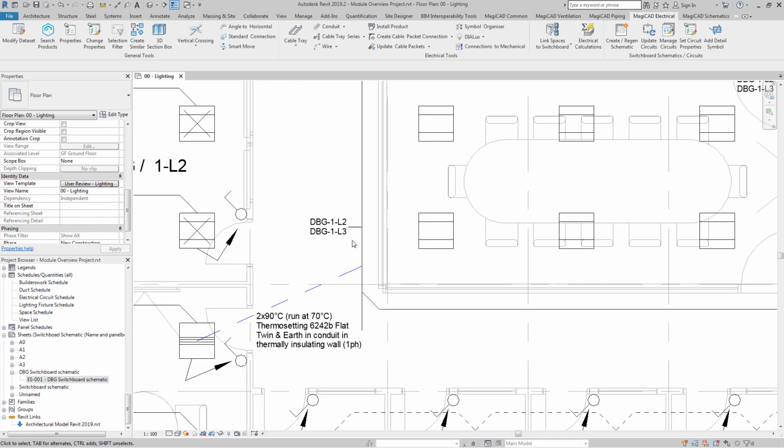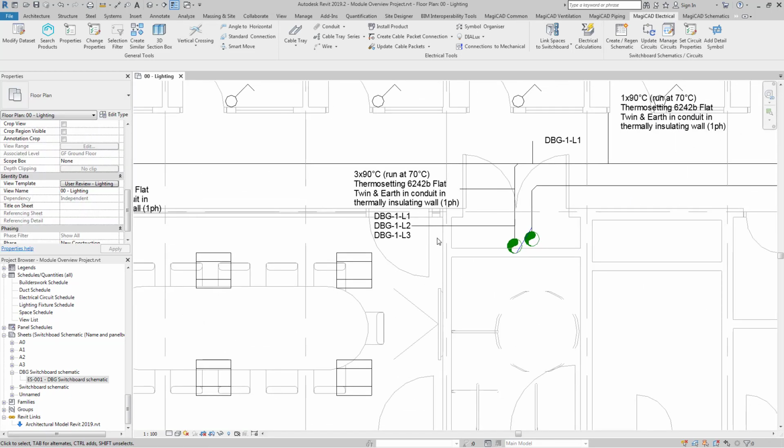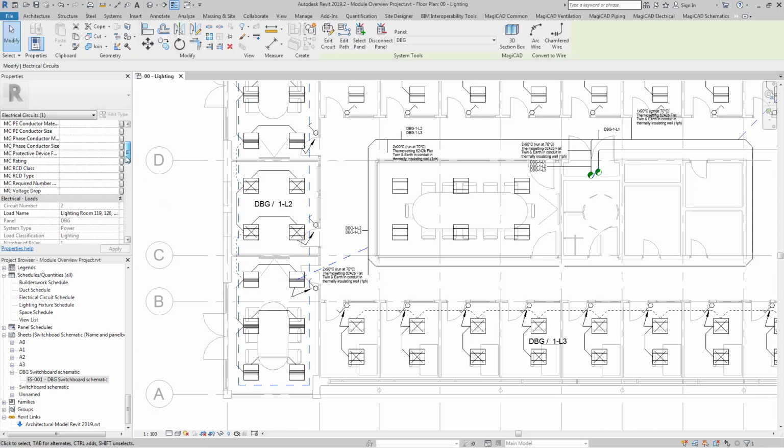With this information, you can accurately size your cable trays, and you can also perform a QA process whereby you're checking that all of the circuits are on the correct routes. And then finally, within this circuit, we can now see we've got the supply cable length detailed here.